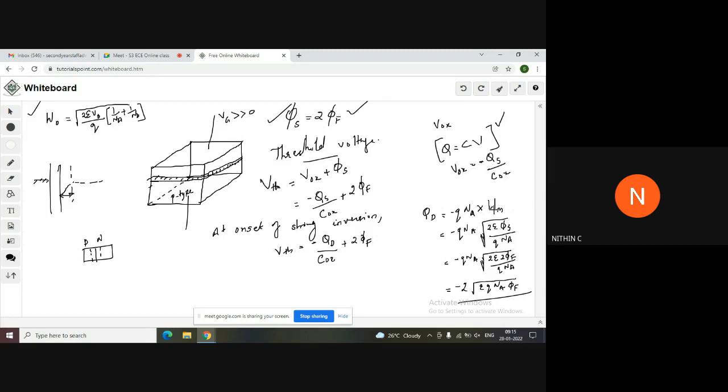Yeah, you have taken the expression for depletion region as this one. This is the general expression, and instead of V0 we need to substitute phi s, because we are considering the p-type semiconductor with surface potential phi s. Most capacitor cases we are not having V0, we are having just phi s surface potential, and then you get the value like this.